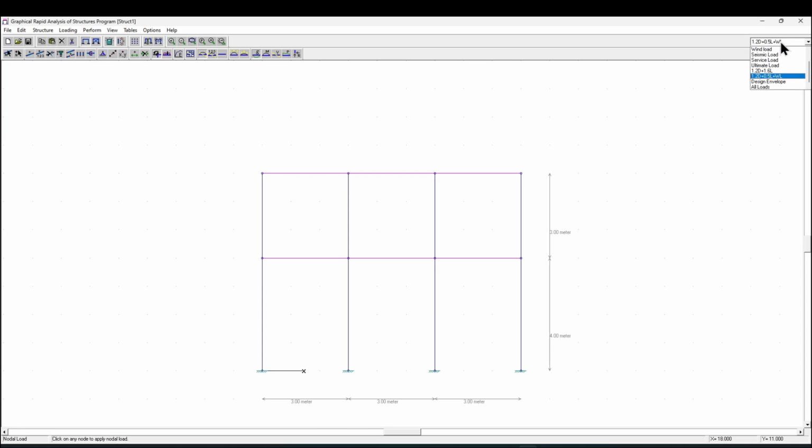Right there it will automatically be added. Of course, this loading combination is directed only for one direction, but in actual design, all you need to do is add more combinations for the opposite direction. After that, you can now input appropriate load factors for the defined load combination.